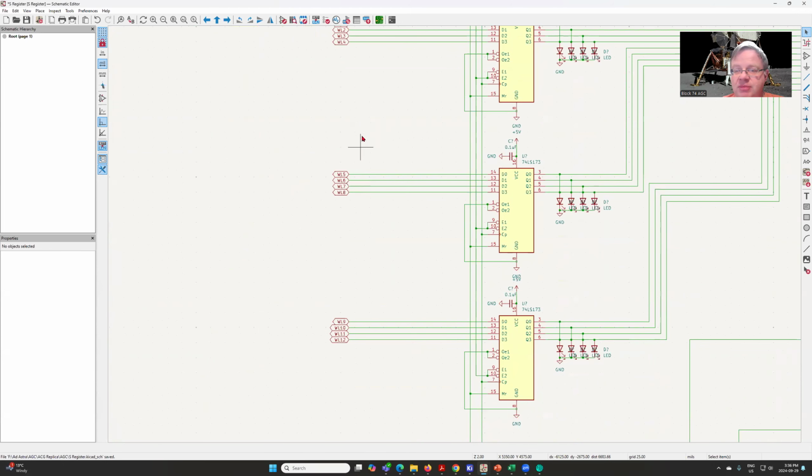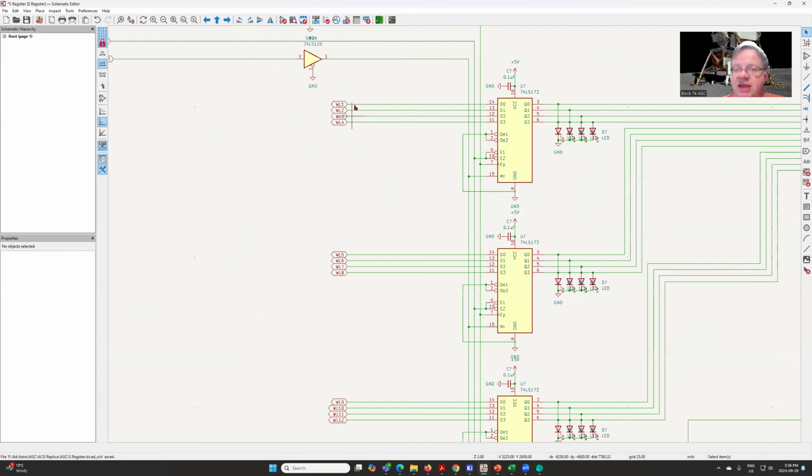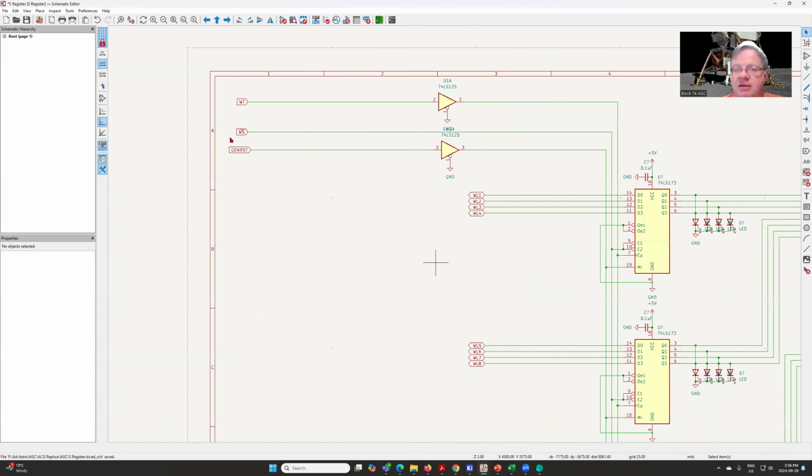And these are fairly simple. They bring in data off the first 12 bits of the write lines. And there's a WS control pulse, which allows us to write data in, so we use that as our enable. And because it's negative logic, we don't have to actually do anything. So it makes it quite nice.